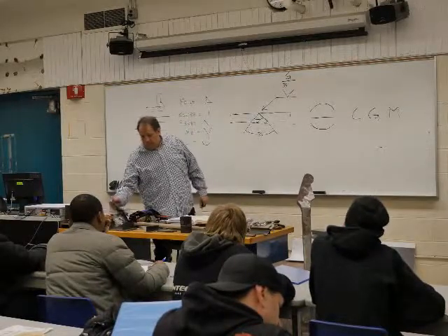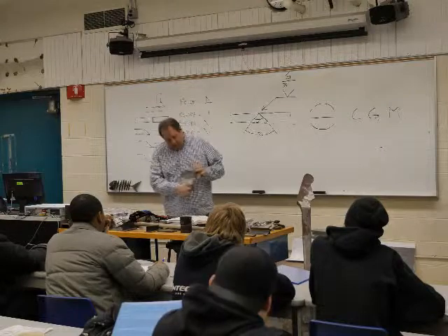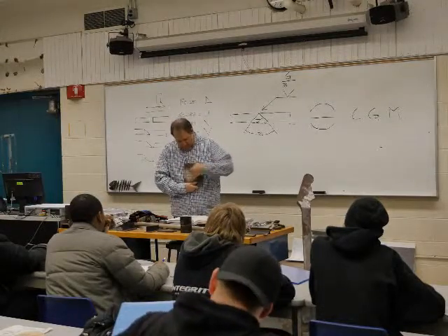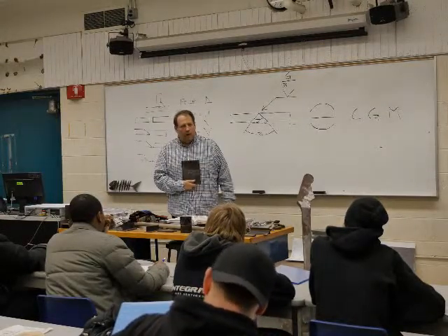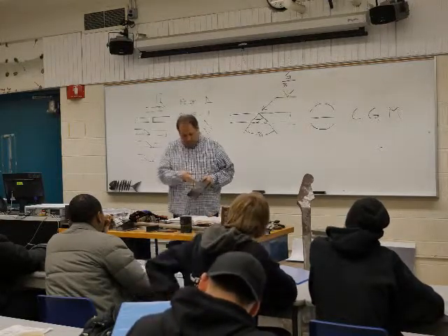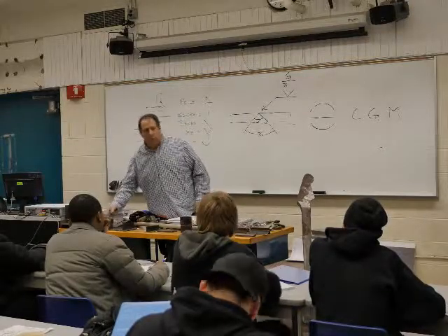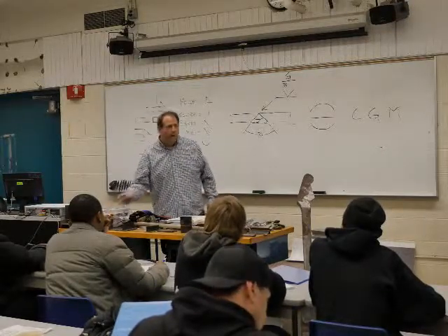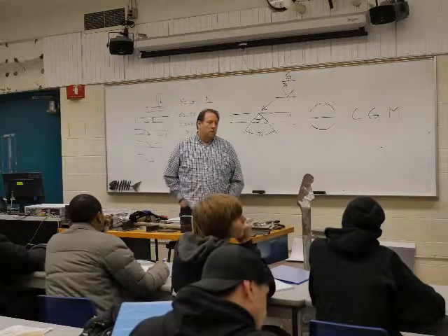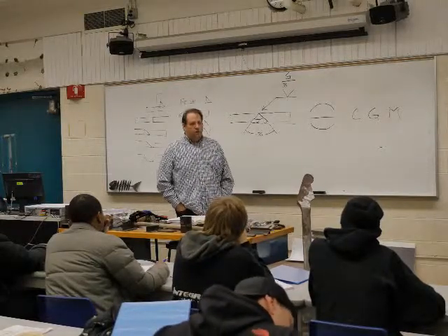This is a ground down surface. So this was a weld right there. Once you ground it down, there were no divots or anything in there. So that would be a finished weld at that point. Yeah. So the line above 75, that's for flush. That's for a flush contour. Okay. Yep.